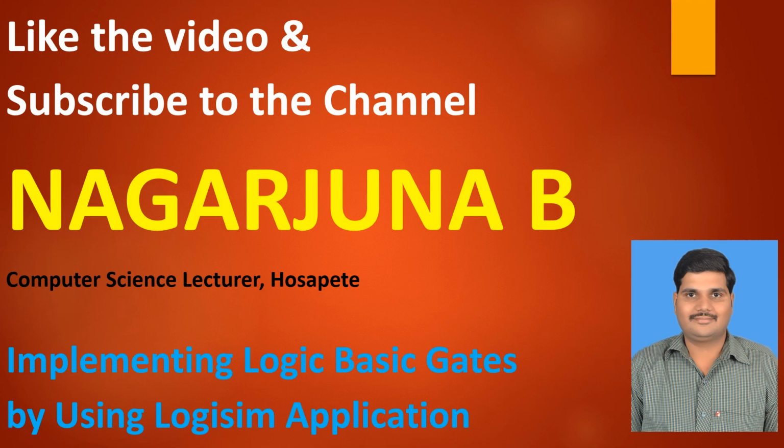In this particular video, I will explain how to design or implement the basic gates by using the Logisim application. At the same time, we shall verify the truth table of our basic gates with the gates which we have constructed. You can use these concepts for implementing the basic gates to perform your logical design laboratory programs.